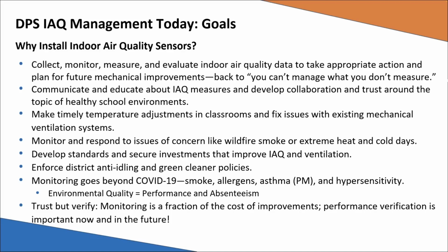Just to touch on why we have taken the path of installing sensors. Basically, back to my very first slide, you can't manage what you don't measure. Past IAQ monitoring was completely reactive, a snapshot in time. Continuous monitoring will provide trends and historical data, and pushes us to a more proactive point with a well-defined IAQ management plan. The first 2 items on this list are the main long-term goals of the sensor network.